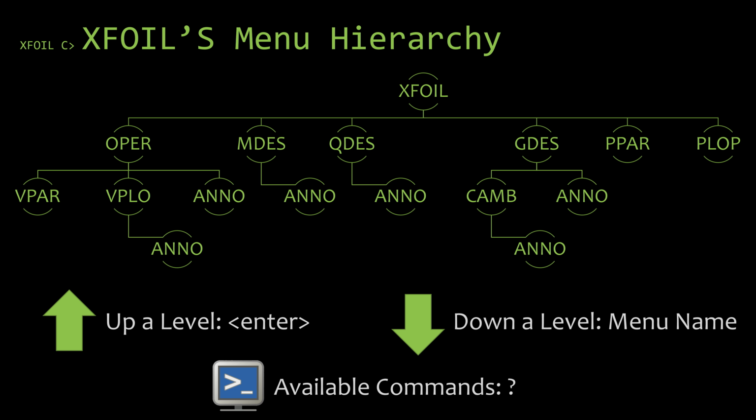So how do we go up a level? In Xfoil, you go up a level by simply hitting the enter button. Now, if you have something written on the command prompt, right, if the command prompt is not empty, then it will try and execute whatever's typed there if you hit enter, right? So if I had just gibberish written down, just a couple letters, and I hit enter, it will try and find the command on the menu I'm at to perform that command that I tried to enter in. However, if I leave the command line blank or backspace these letters that are there and then hit enter, then you'll see that it'll take you up a level.